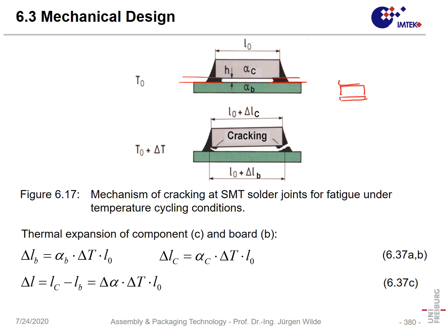We will have the pads with the solder in between, and if we have a delta T, we have again the pads with the solder in between, and here we have a shear deformation, and that shear again will lead to phenomena which are not really desired.